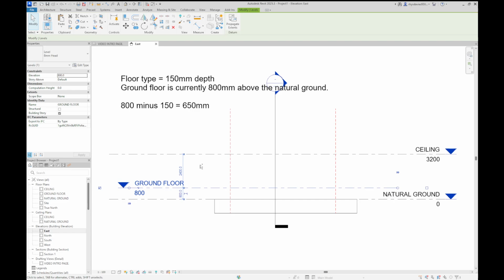The cursor changes shape a little bit, and a little plus appears next to it. That is the control key doing that, and what that means is that I can add to my selection without letting go of this one here. So this one's selected. If I control select, I now have both of those levels selected.